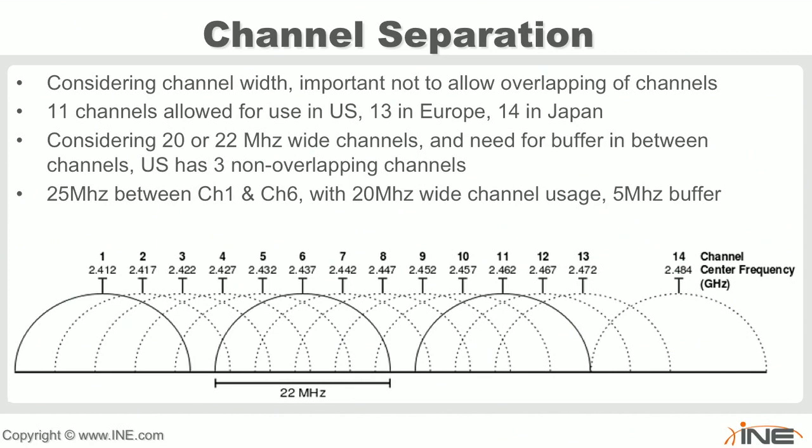Wow. So we talk about 8 antennas, 160 megahertz wide channels, and 256 QAM, or quadrature amplitude modulation. And then you can begin to see how we're pushing. So we're using multiple different things. 8 times the width of an 802.11g channel, really 8 times the width of a standard 802.11n channel. Most don't use 40 megahertz, most use 20.